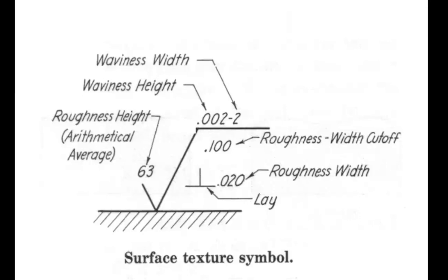If in the vicinity of the projection of the surface there is an available empty space, directly bring the surface finishing symbol with its tip into contact with the edge of the surface, and then write the necessary numbers and show the lay direction symbol.